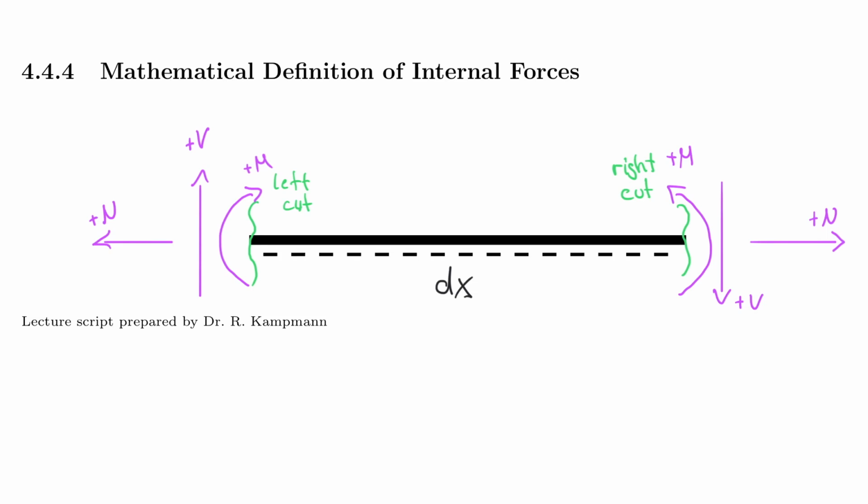And remember something that you have seen in your homework. You may have not known why it was there, but sometimes you've seen that there was an x direction given with that pointing arrow. Now, why is that important? Because later on we will express the moment as a function of x, the shear force as a function of x, and the normal as a function of x. So sometimes you would say, like before we said in terms of c, right?